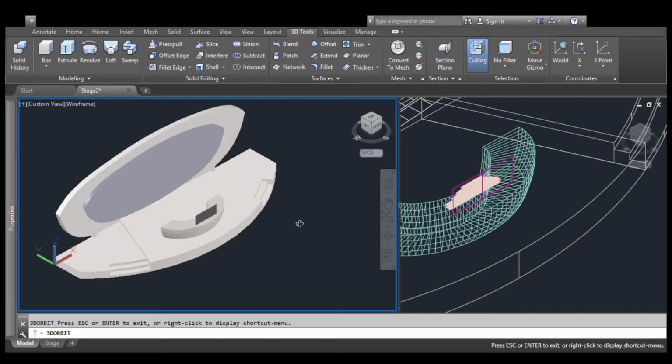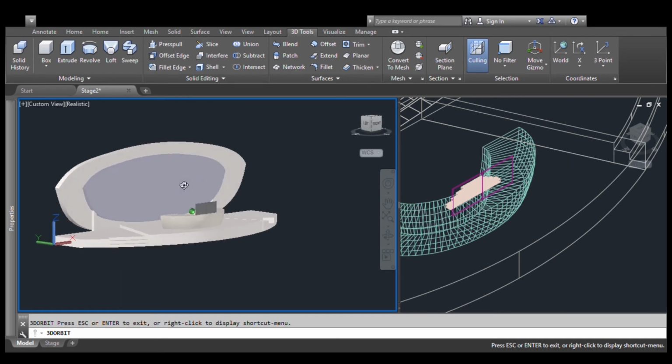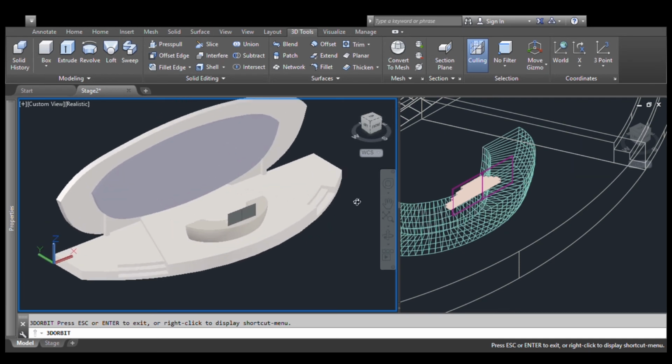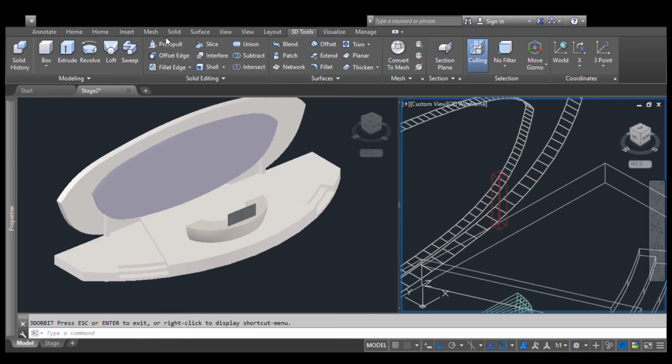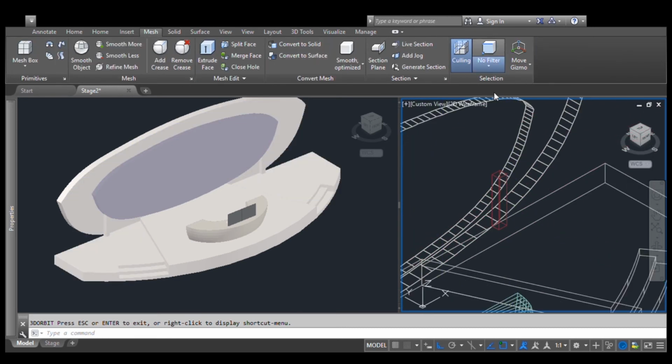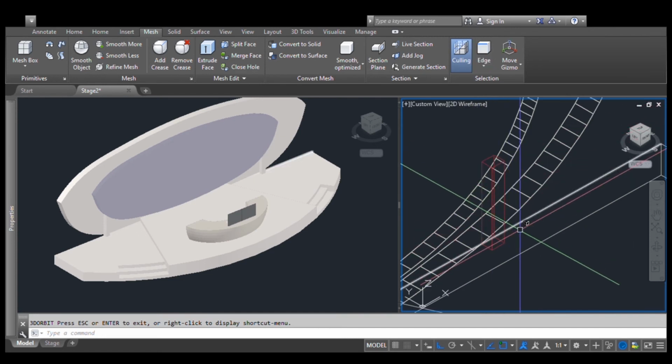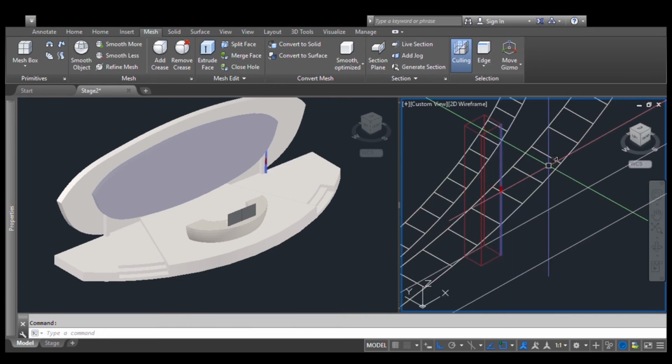And here, so I just change the color of the edges by using this command here, mesh, and then edge, so that I can just select directly the lines of every element and then change the color to properties. Or another way is I can change it to layer. I will make it by layer, by object.